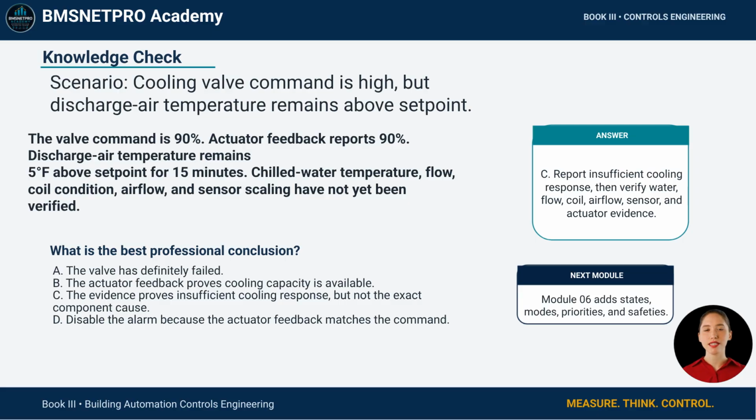The valve may be commanded high and actuator feedback may track, but chilled water temperature, water flow, coil condition, excessive airflow, sensor scaling, and load must still be verified. A professional alarm reports the observed outcome and probable causes. It does not falsely name one failed component when the logic has only proven a failed response.